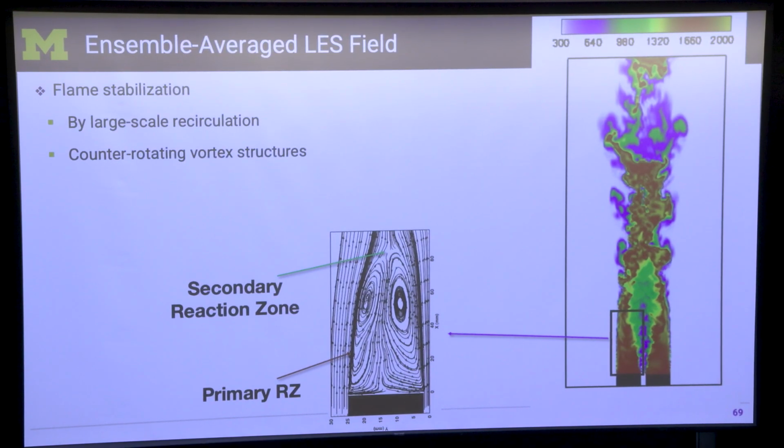So that's the instantaneous picture. If I take it, time average it, and run Lagrangian particles, I would get these streamlines. And if you did experiments and you take PIV and do the same, you'll get exactly the same picture. But they're coming from a highly unsteady flow where the structure is changing all the time. Yeah, so there's a difference between the two.